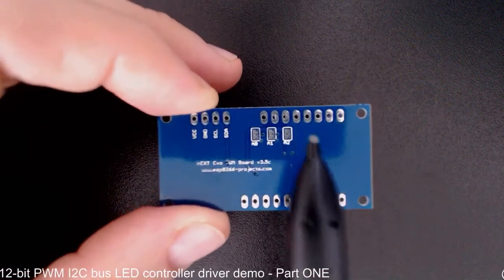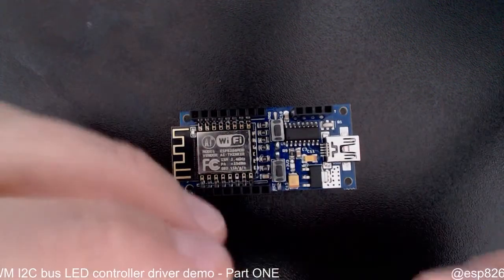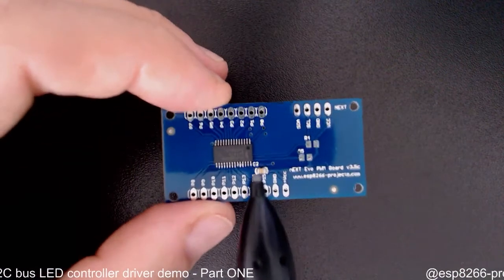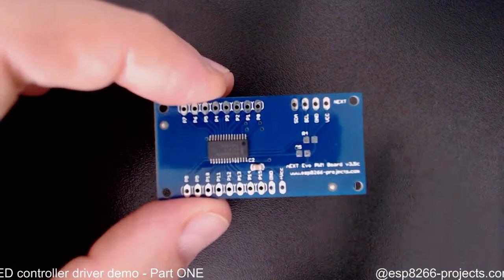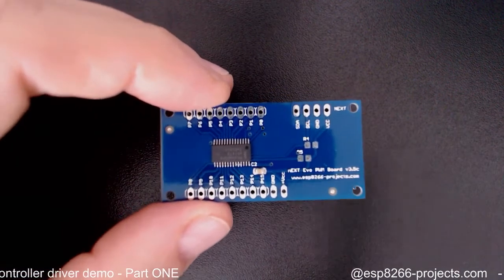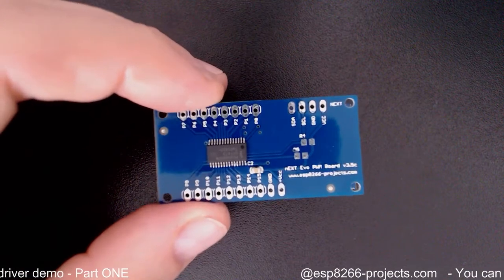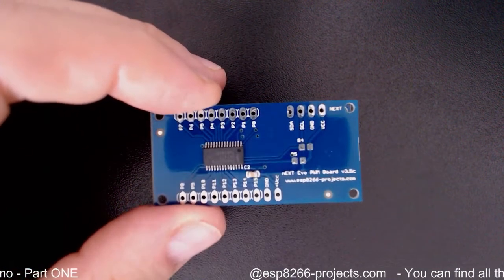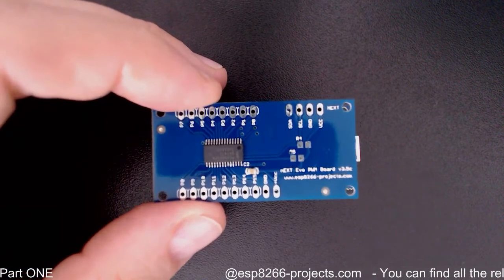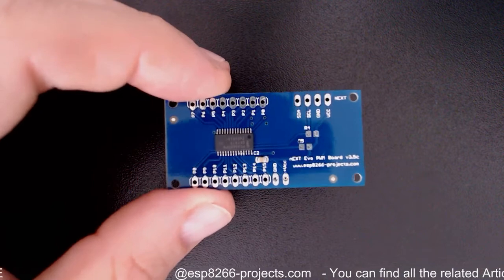Or, of course, you can have multiple PWM extension boards, and you can choose a different I2C address for each one, and you can end up, if necessary, with up to 128 different PWM channels. This is quite a big number actually.